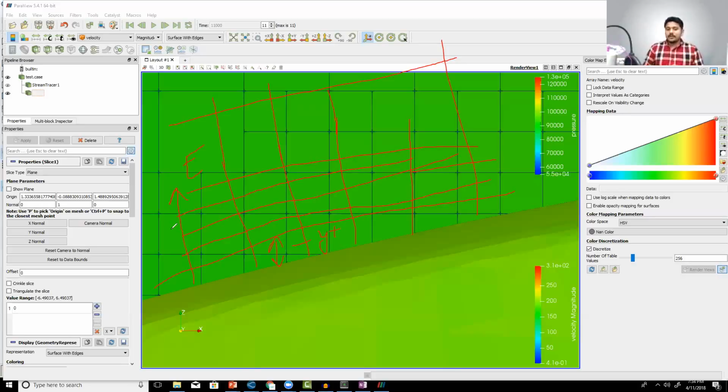Whereas in transient simulations, you are caring about each and every time step. An example would be IC engine simulation. Only if you're getting your intake stroke correctly, your compression stroke would be correct. Only if you're getting compression correct, power stroke would be correct. Whereas in an airfoil, it's not like that. Your drag coefficient will start out wrong initially, but as the flow converges, it will settle down to the right value, which is a steady value. Does that make sense, Shazad?